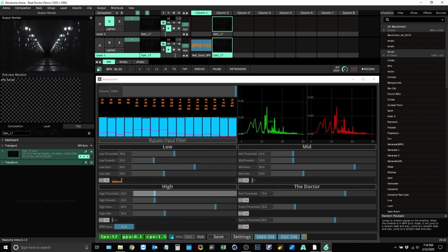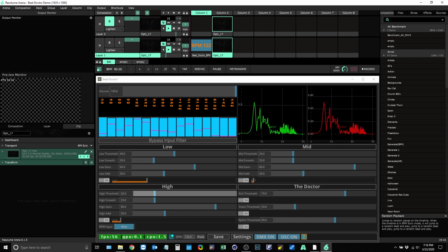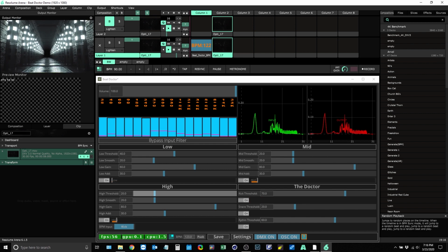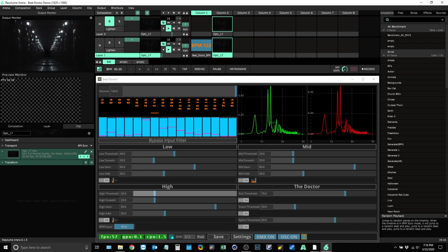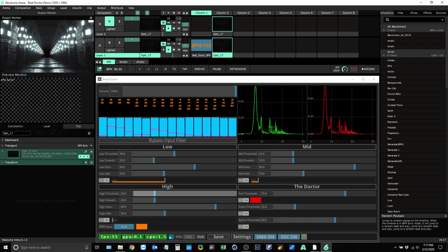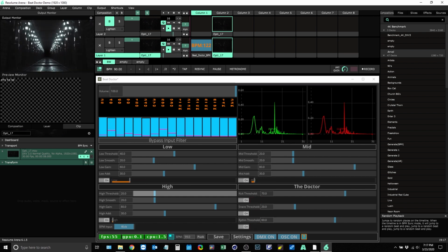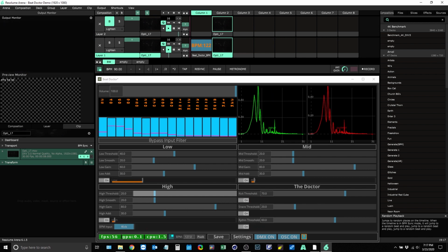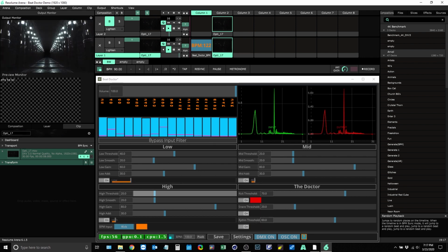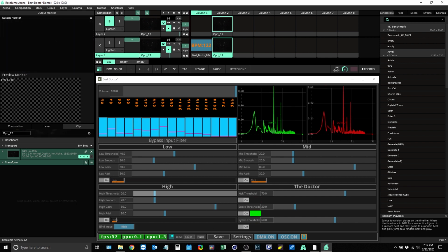I like the audio just to be turning green, maybe just a slight hint of yellow or amber on your hardware's readout. That'll ensure that your hardware is not clipping. Clipping is never a good thing, overdriving your audio signal, but it also ensures you that your signal is not too low, so I don't have to do any sort of digital boosting. From that point on, your front of house audio engineer, he knows what he's doing, or she knows what she's doing, depends on the situation. So they'll keep a constant level coming to you. It shouldn't drop more than maybe 3 dB plus or minus.